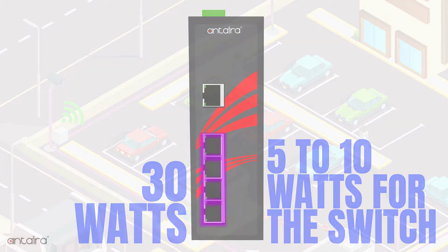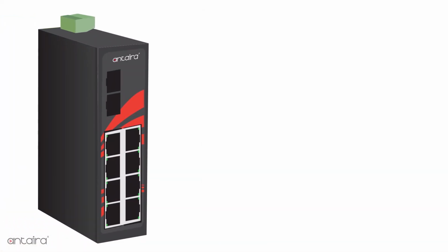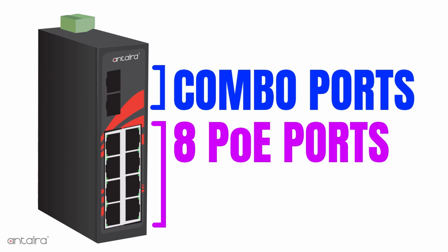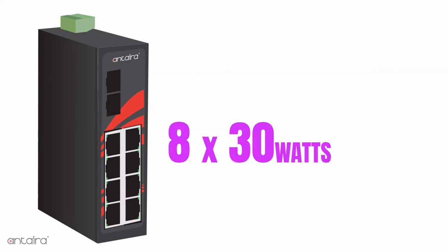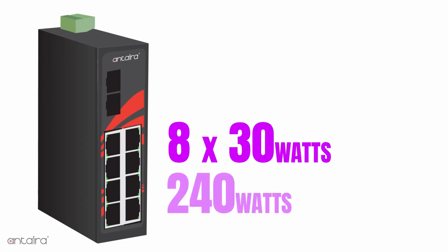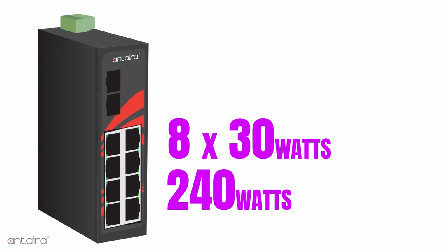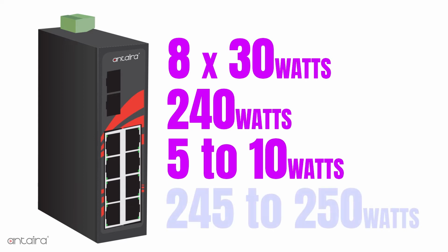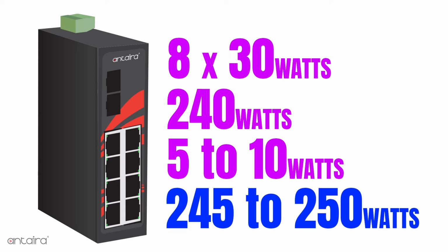Let's say that you are using one of Antaira's 8-port PoE switches with 2 additional combo ports. Using this method, you would calculate 8 times 30 watts for the PoE power, which is 240 watts, plus 5 watts for your unmanaged version, and 10 watts for your managed version. This would give you somewhere between 245 to 250 watts.